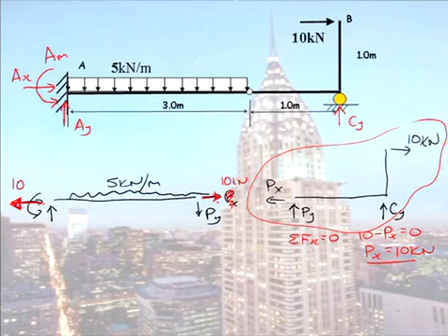So moving back to my free body diagram on the right now, I know the 2 forces in the y direction equal 0. That's not telling me anything, however. So I'm going to take moments next, and I'm going to take moments at the pin. And doing so will help me calculate CY. So that's 1 metre. Both distances are 1 metre.